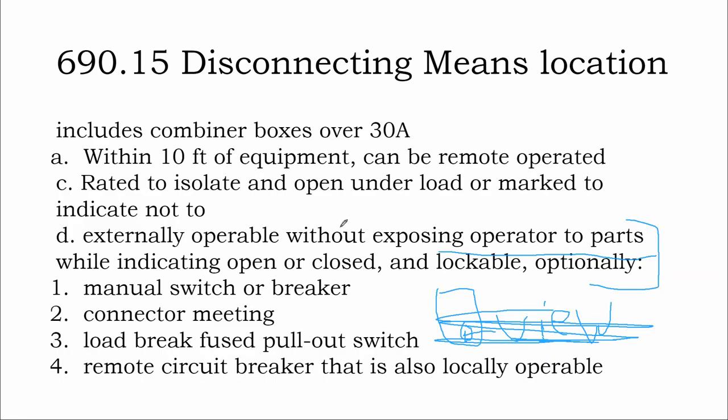That knife switch disconnect where up is on and down is open, that you can just pull up to the side of the house and look at that knife switch to see if it's open or closed. That's an indicating, lockable, operable switch. A knife switch is not the only switch that is allowed by code to be this disconnecting means. It's just a very common one.